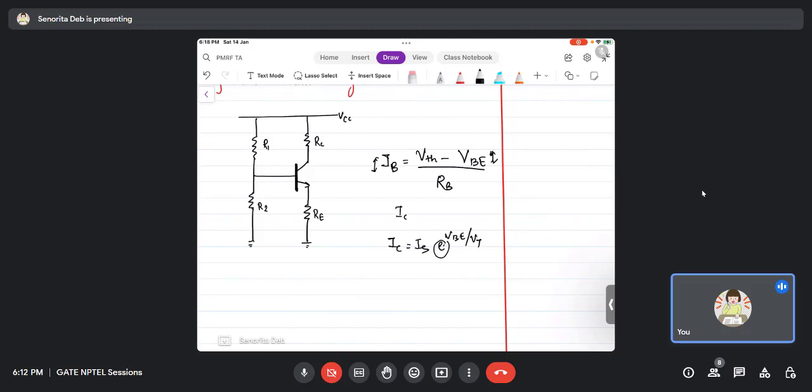So now what will change with respect to temperature? Two things will change: either the BJT's beta will change or the resistor R. Now R variation is more prominent because of the temperature dependence, right? Suppose the beta variation is happening and correspondingly the external resistance variations start happening. So first let us focus on the external resistance variation.